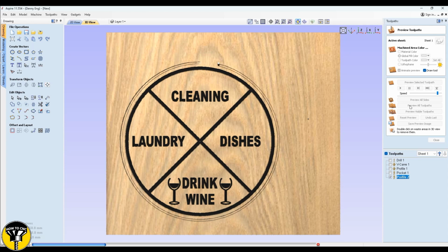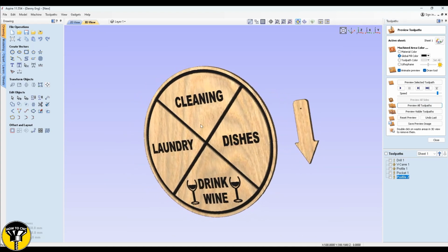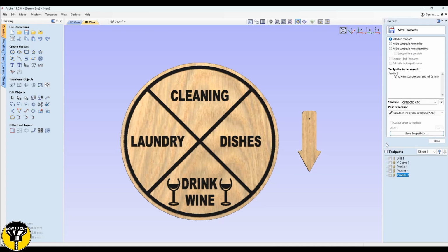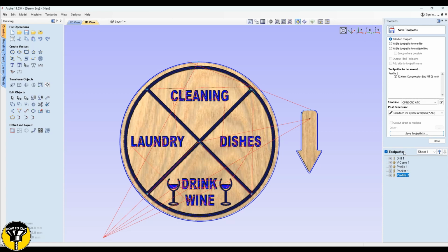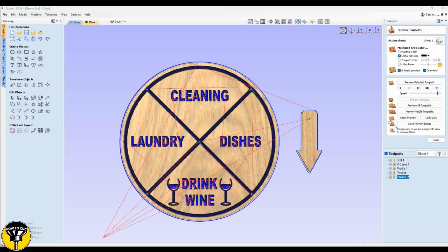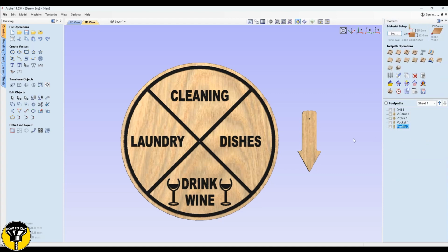Now here's doing 3 passes around the outside. And this is the finished file. If you want to save your toolpaths, simply head over to the save icon, select the toolpath button. Now you can save them individually or all as one if you have an automatic tool changer. Click Save Toolpath and you plug your USB into your machine and away it goes.